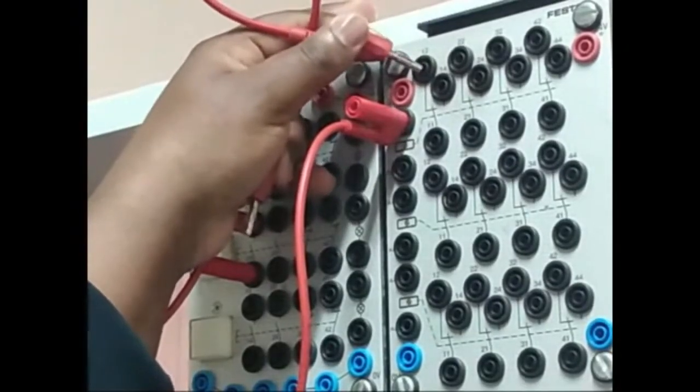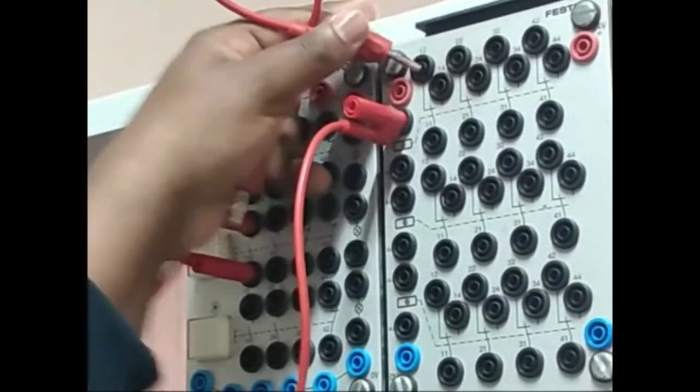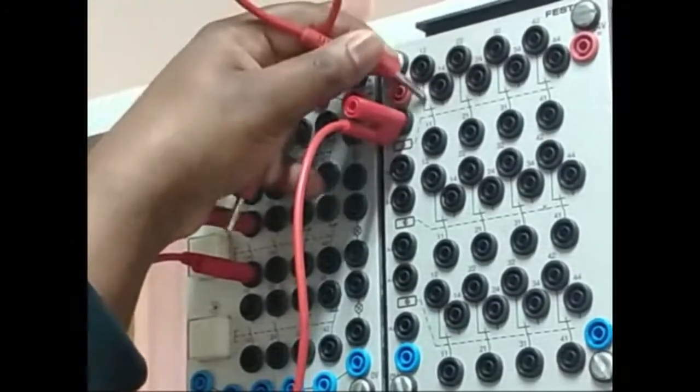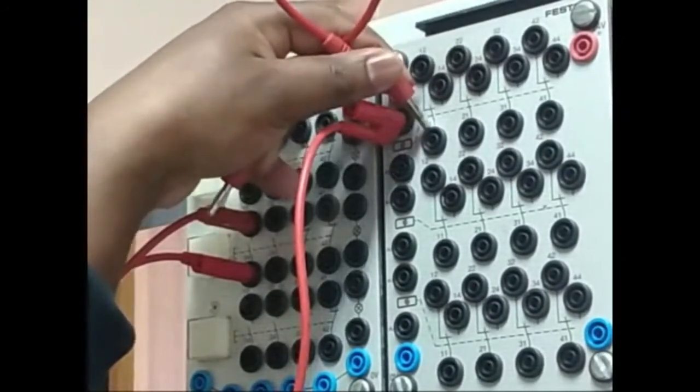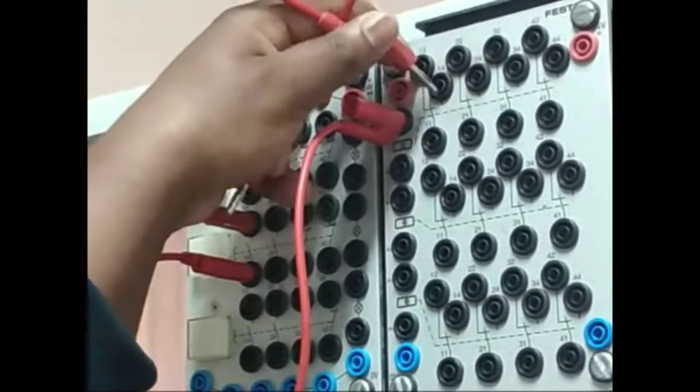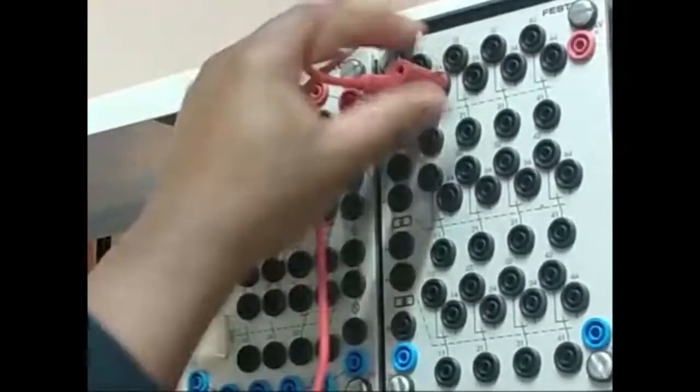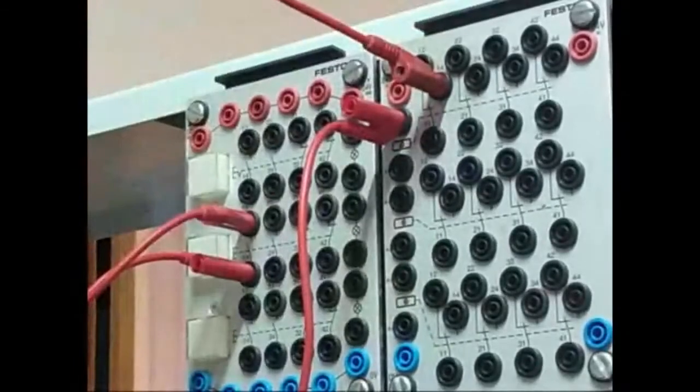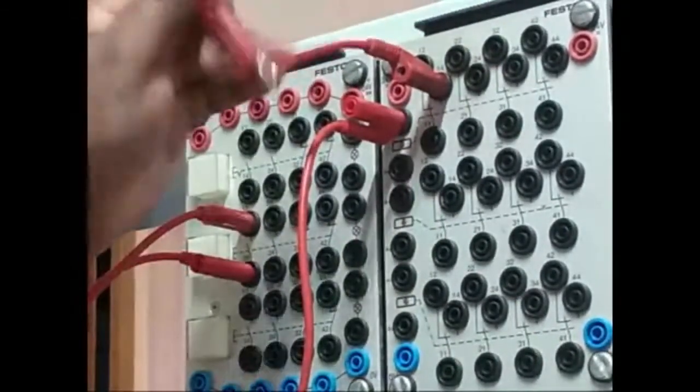If you are drawing this, you can just refer to your screen. We have 12 there. That is a closed circuit with 11. So we cannot use that 12. We're going to use 14 because 14 is open. It's going to only actuate when we give it power.